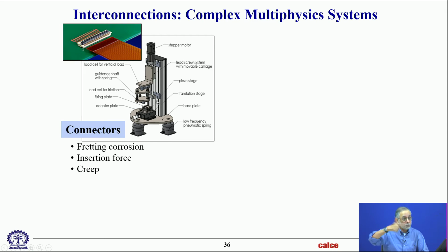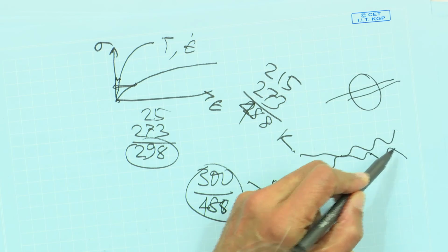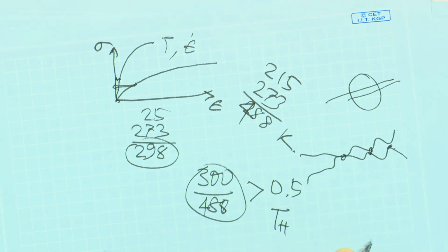The gold is A, preventing corrosion, but B, you need a soft contact. You cannot have a hard contact surface in connectors. Does that make sense to you? If you have two hard surfaces, what's the problem? Surfaces that look smooth to the naked eye, I'm going to write again. So two contactor surfaces that are making contact like this, in reality, if you zoom in, is one surface like this and another surface like that. If these are hard surfaces, then they're making just point contacts.